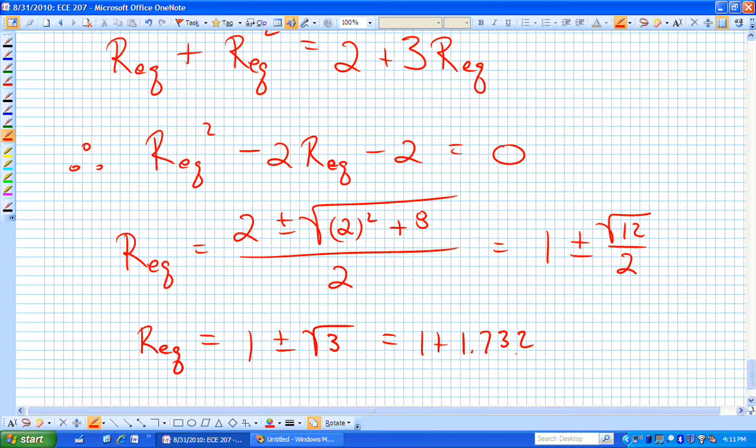Oh, thank you. I don't need you to know it for more than a couple. Is that what we were guessing our resistance might be? Somewhere between 2 and 3? And it is, isn't it? It's between 2 and 3. So that satisfies our suspicion, our warm fuzzy feeling that that is the right answer. So if we put an ohm meter on that infinite ladder network, it would measure 2.7 ohms.